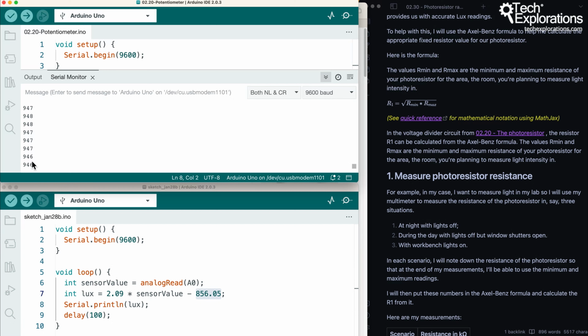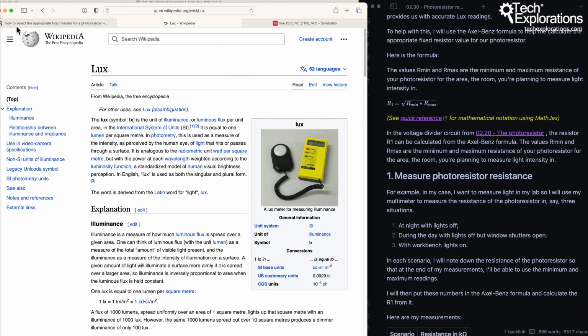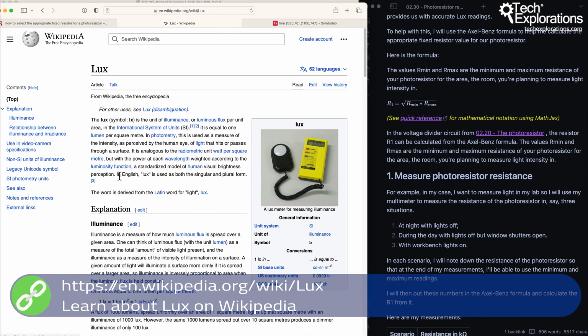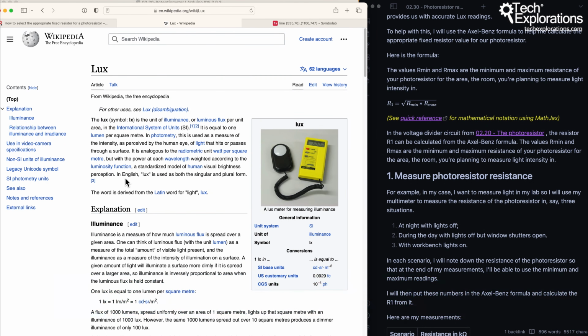It's a value that represents the voltage on analog pin 0, and of course it varies depending on the ambient light that is hitting the photoresistor. But on its own, this number doesn't tell us anything about how much light there is in the environment. In this lecture, you will learn how to convert the sketch and potentially the circuit as well, so that the number that comes out relates to an actual illuminance value and unit.